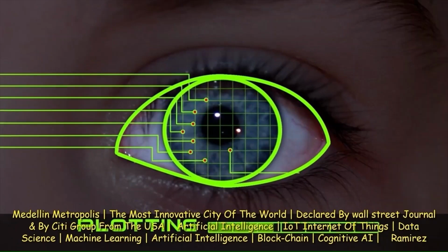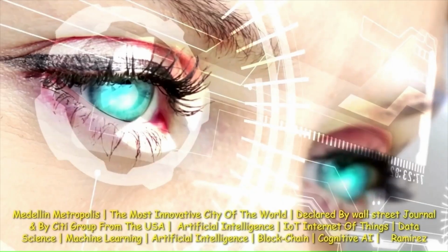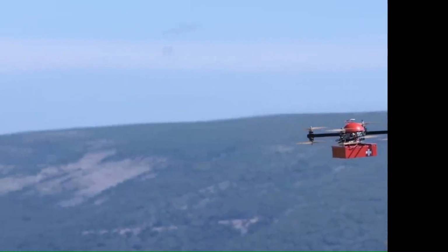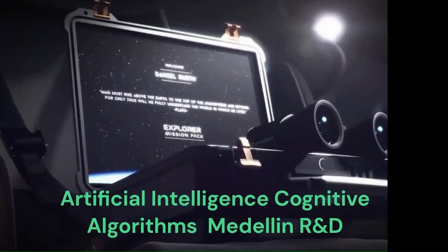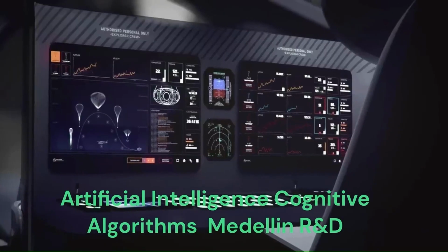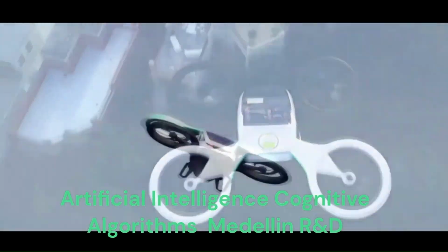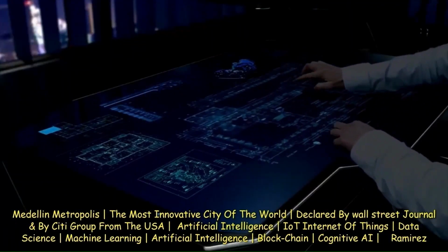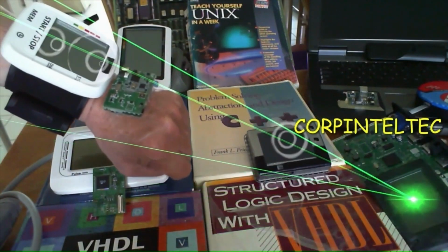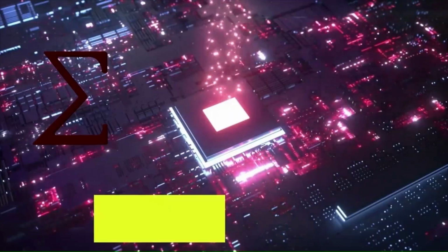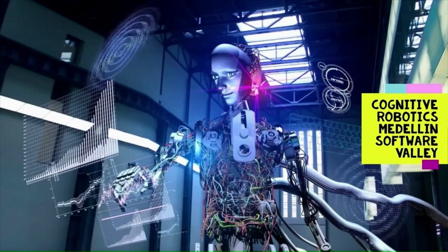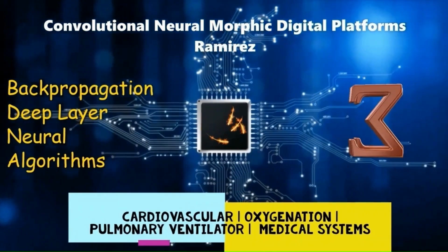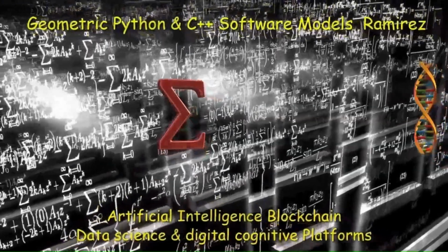This unit consists of a 3-axis gyroscope to read angular velocity and an accelerometer to measure acceleration and force. This type of combination is known as 6DOF-IMU. In this way, it senses the orientation of the quad.